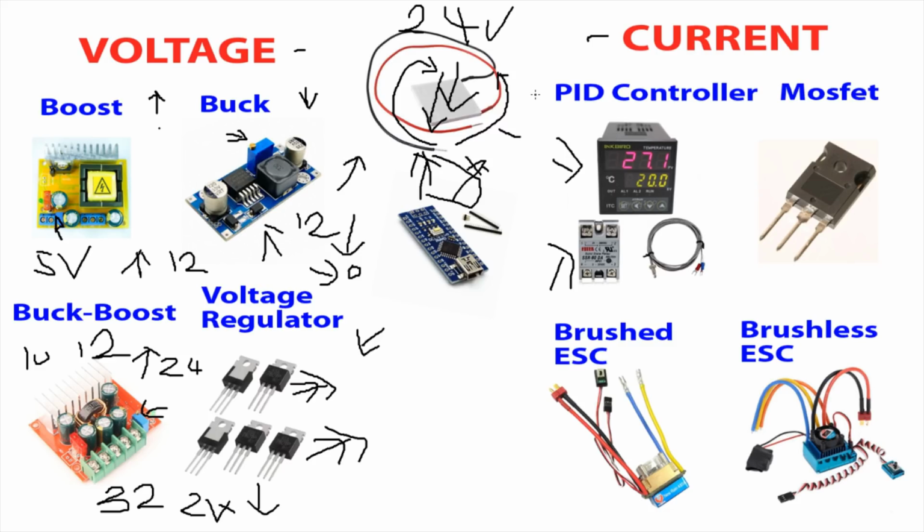So the TEC should last a lot shorter, be less reliable if you use a controller like this. But that is the easiest way to control it. It's out of the box, you've got a little nice screen, you can program it up, plug your SSR in, and you're all done.